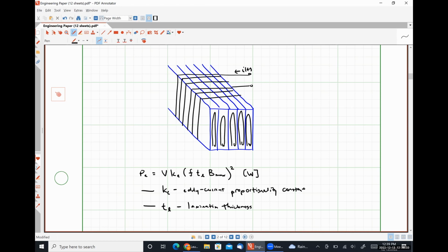One thing that I do want to talk about here, just very briefly, in this class, we're going to view eddy currents as, generally speaking, a pretty bad thing, but in practice, they're quite useful, okay? Eddy currents are how train brakes work. Effectively, a time-varying magnetic flux is passed through the wheel of a train because they're typically a big cast iron plate. That flux induces a current, which causes the plate to heat up, and that heating up causes the train itself to lose energy and gradually slow down. So it's how you get very soft deceleration instead of a hard braking in a train.